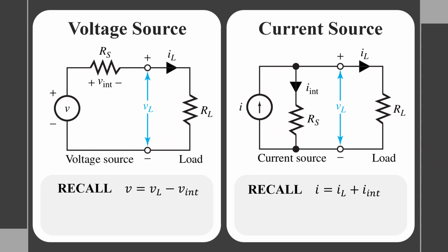The wire diagram indicates the internal voltage drop within the source, which depends on the amount of current drawn by the load. The voltage seen by the load is somewhat lower than the open circuit voltage of the source, and when the load resistance is infinitely large, the current goes to zero, and the load voltage is then equal to the open circuit voltage of the source voltage. Hence, it is desirable to have as small an internal resistance as possible in a practical voltage source.